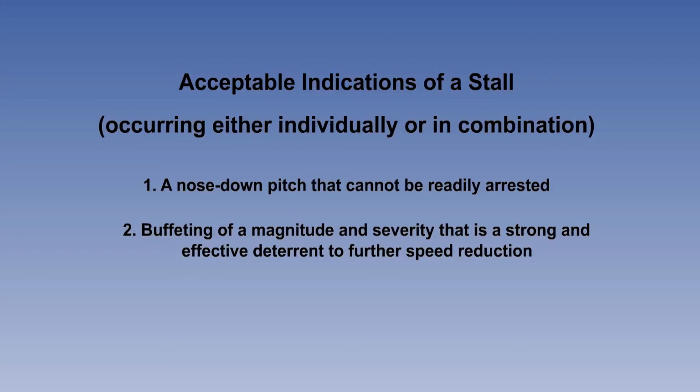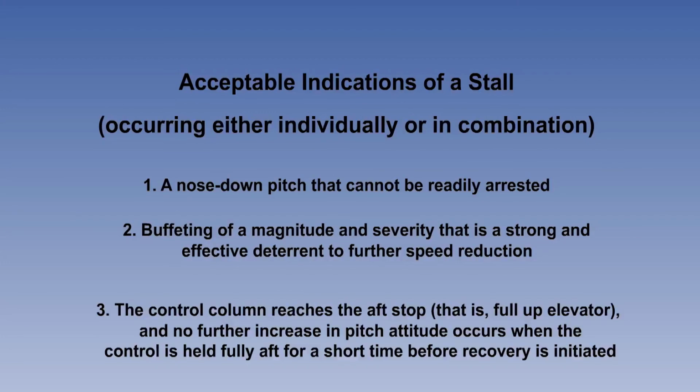2. Buffeting of a magnitude and severity that is a strong and effective deterrent to further speed reduction. And 3. The control column reaches the aft stop, that is, full up elevator, and no further increase in pitch attitude occurs when the control is held fully aft for a short time before recovery is initiated. The following section of the series of lessons deals with stall speeds and warning and prevention devices.